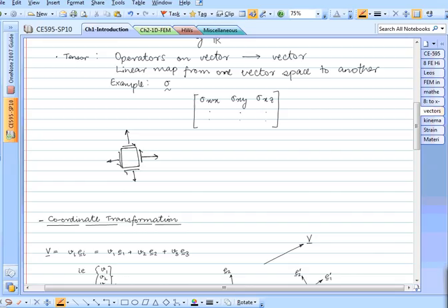And now if I rotate my coordinate axis, let's say by 45 degrees, I'm going to get a different set of stresses. And the relationship between all these different sets of stresses was our Mohr's circle.